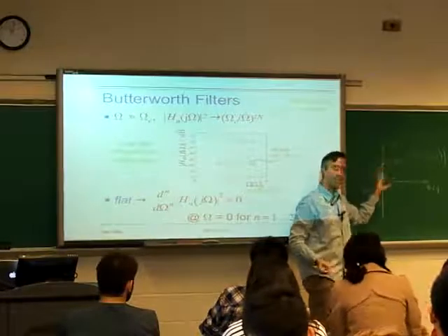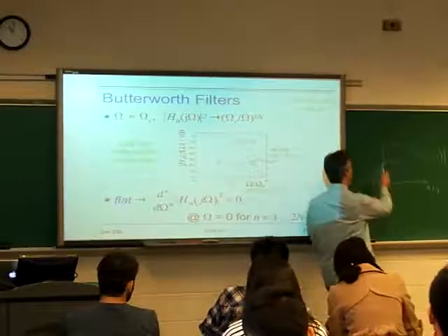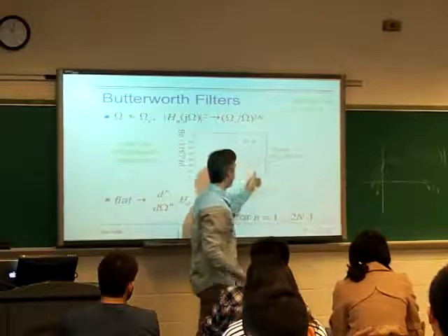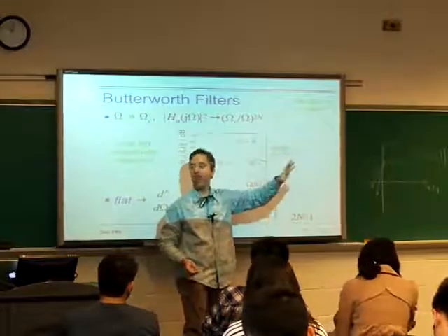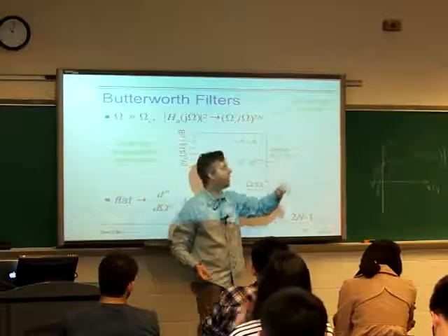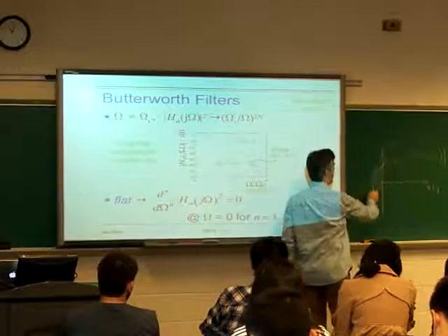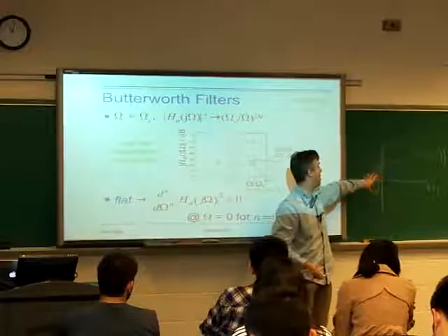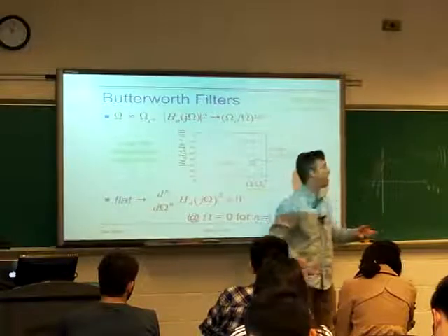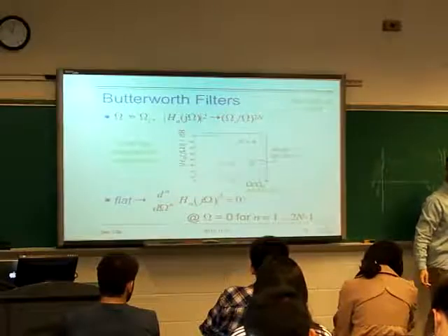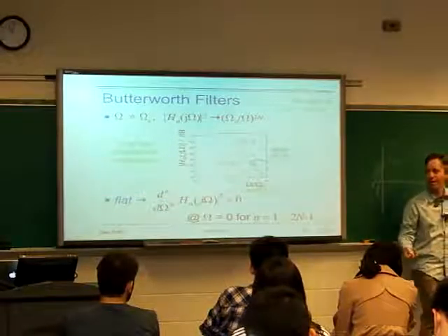As my frequency goes up, typically when we're in this slope here, we're not close to any of the poles anymore. We're going off into higher frequency. What happens is all of these lines are getting longer, and it doesn't matter where the poles are exactly, they're all getting longer now. And so we get 1 over this thing, which is approximately just the frequency, right?